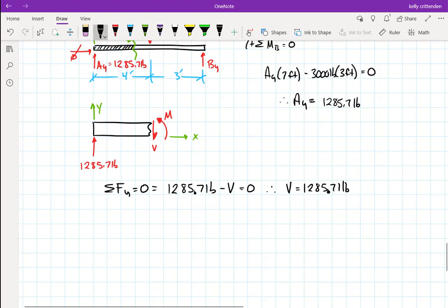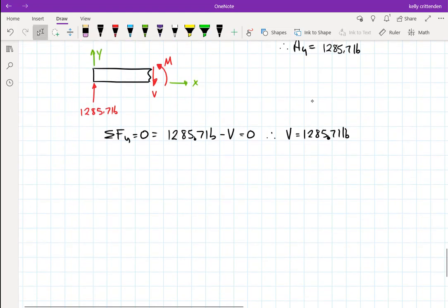There is also a different shear that we're not going to look at in this course, but if you're mechanical or civil and you take continuation courses, there is a shear that's not even shown on here that could also affect things. We're more interested in this M. So what I would do to calculate M is do a moment somewhere, because that's where it's going to show up. So I'm going to do summation of moments about this cut surface, just so I don't have to deal with the shear force. Let's say that counterclockwise is positive, since I drew M counterclockwise. They still need to add to 0.